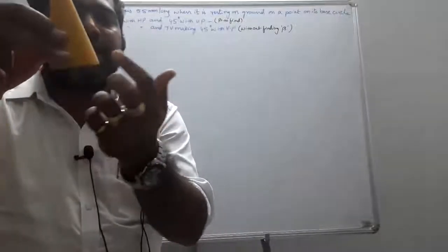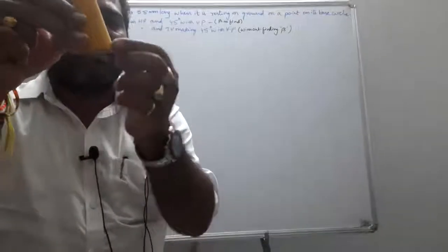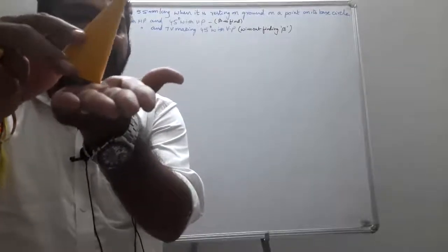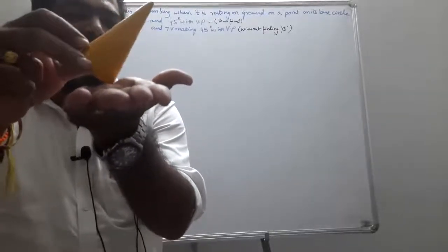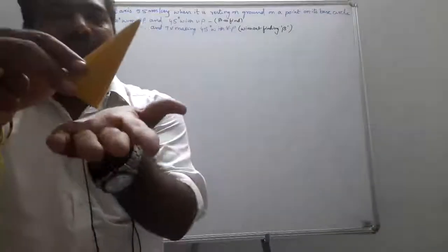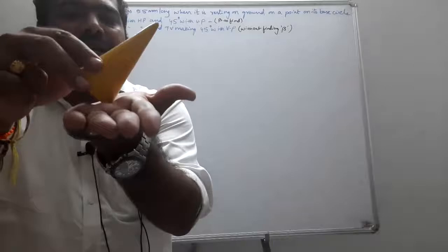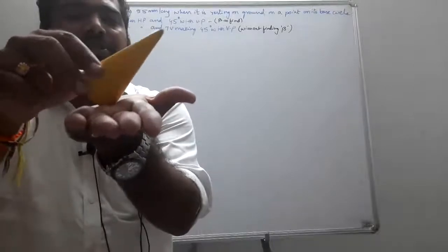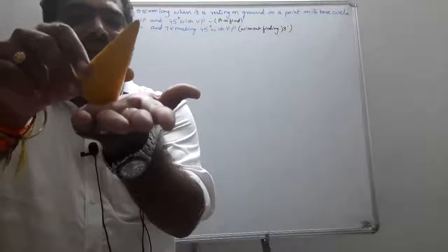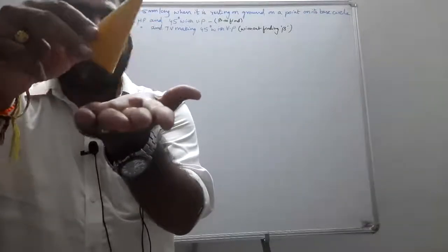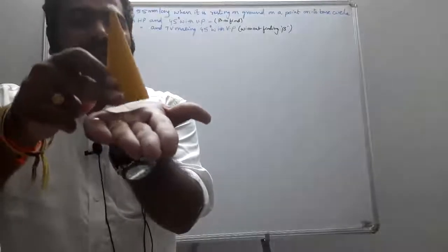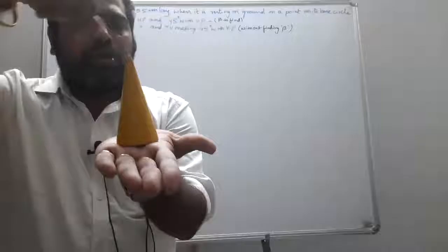Let us consider this was a base circle. Let us consider any point, and at that point it is going to be tilted at an angle of 30 degrees. That means the axis is making an angle of 30 degrees to HP and next 45 degrees to VP. First of all this and then this. So the first stage is axis inclination. In simple version, let us put the axis perpendicular to HP. Top view gives the true shape.